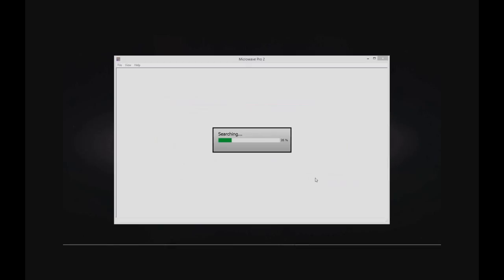Now, when you hit OK, it's going to go out and search the ULS database and find all of the paths that have a co-channel or first adjacent frequency relationship with the reference path that we put in. It takes a little while because there are a lot of records. Essentially, it searches through a shortened version of the database that just contains the coordinates and the frequencies and such, and determines which records it needs to load. Then at the end, where it says building records, it's pulling in the other data, like the contact info and various other data associated with the paths that it didn't load on the first pass.